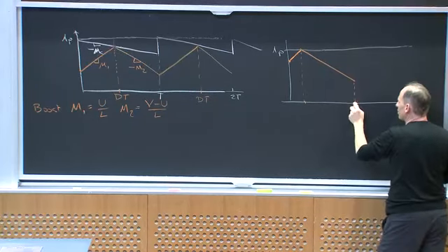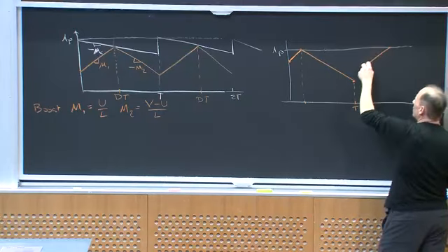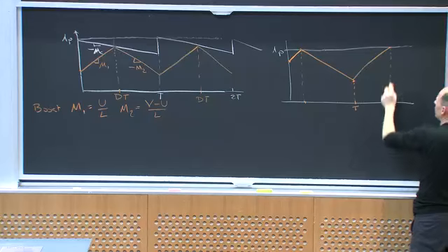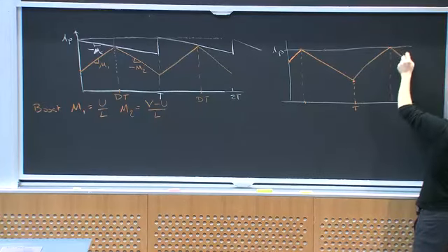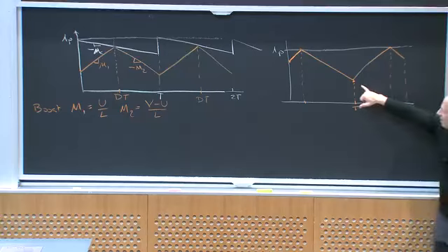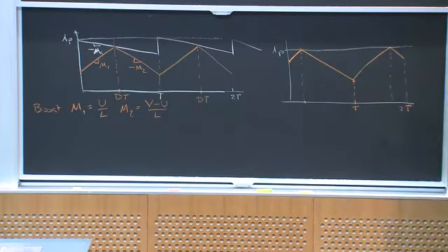And here's the end of the cycle, here's capital T. And now I turn my inductor current on, and it ramps up. It hits here. Here's my duty ratio in this cycle. And then it turns off, and I hit the end of the cycle, 2T. And you can see that I don't settle down into periodic steady state operation at the switching period. In this example, it sort of repeats every other cycle.